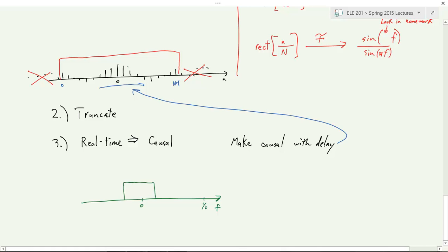So it was mentioned last time when we were doing a different signal. We had a signal that was on and then off. And someone said, so what we've essentially done is we've zeroed out everything out here. So you can interpret this as multiplication by a rect. Okay, we've taken our original signal, we've multiplied it by a rect, which means in frequency we are convolving with this sinc.